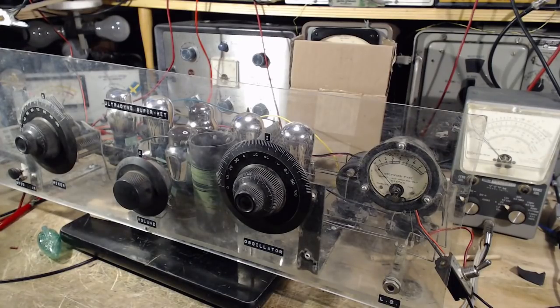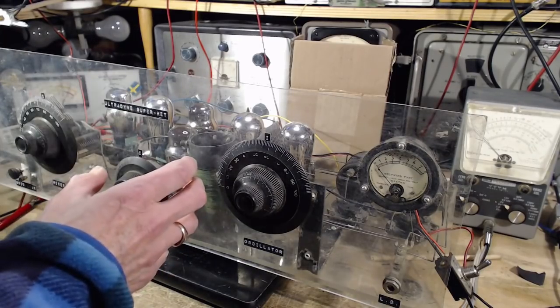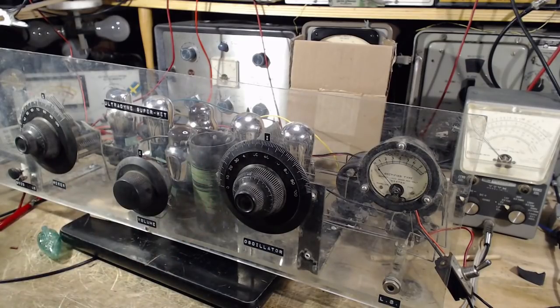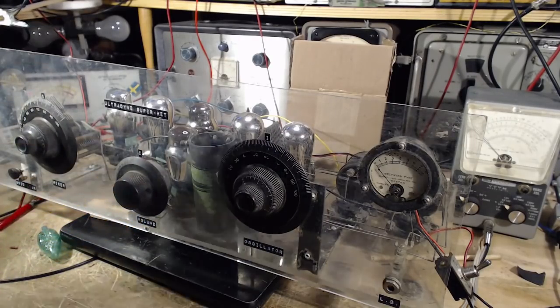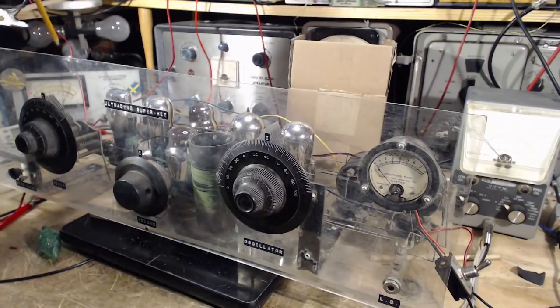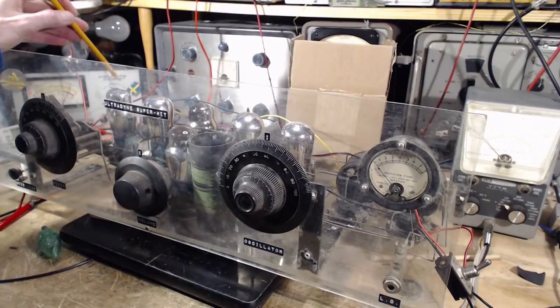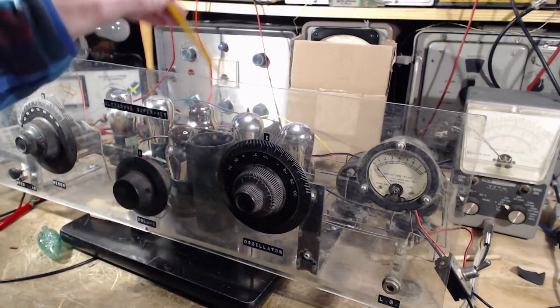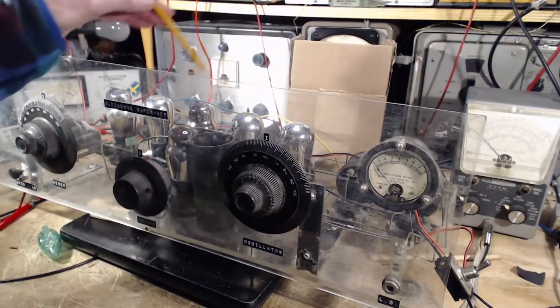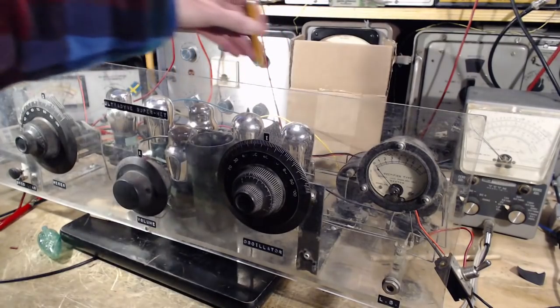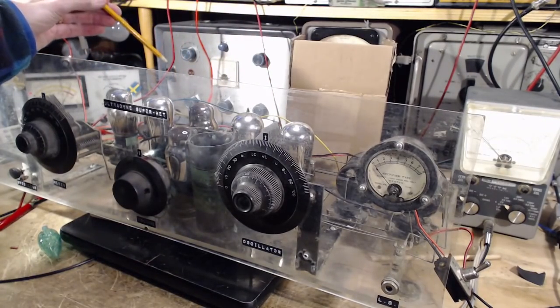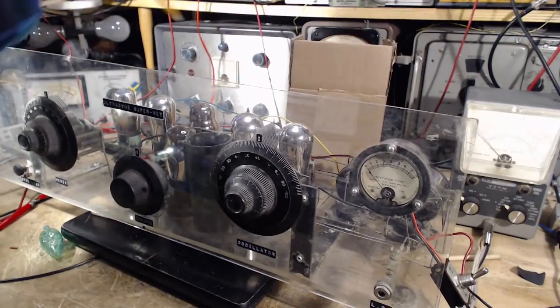So assuming that's correct, that it wants to oscillate but it can't, what would I do next? We could leave the oscillator for a minute, and we could work on the very front end of the radio, but I don't think I want to just yet. We could try to pass an IF signal through the IF and see if it gets all the way through. We could then align these a little bit, align these transformers here a little bit.